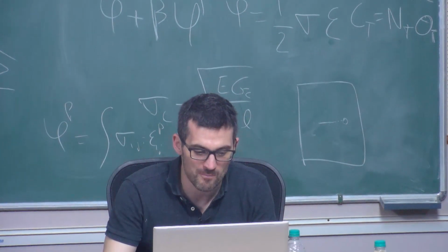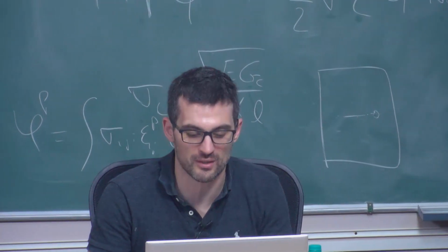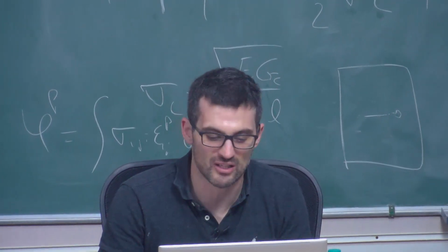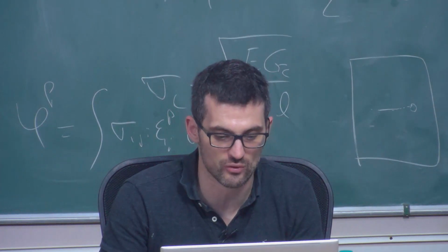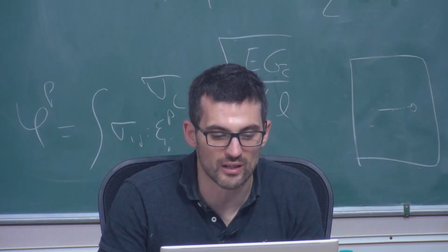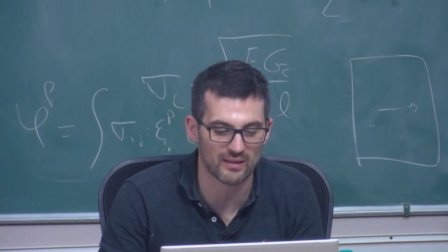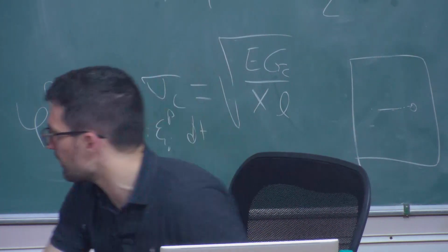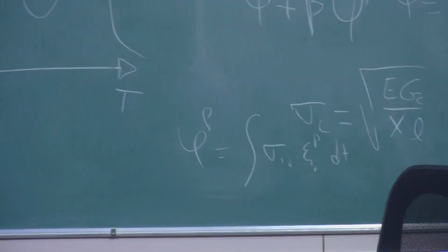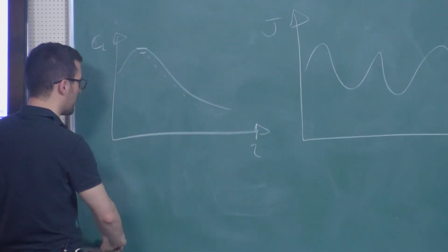And you can see here that if I change the frequency, or this normalized frequency, basically it's a competition between frequency, some sort of length scale, and your diffusivity. This is the normalized frequency. So if you do that, you see that if you load very, very fast, so the pink line, then there's not enough hydrogen. The hydrogen doesn't have enough time. So basically, what happens in the hydrogen ahead of the crack tip is something like this, right? You start here. Let me plot it a bit better.